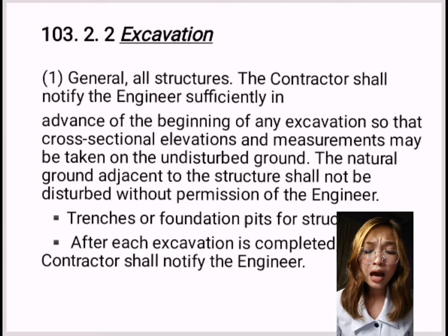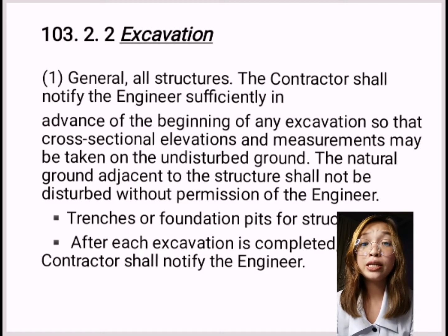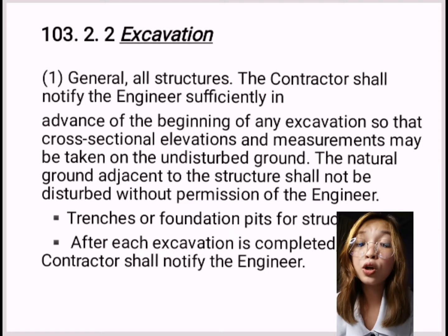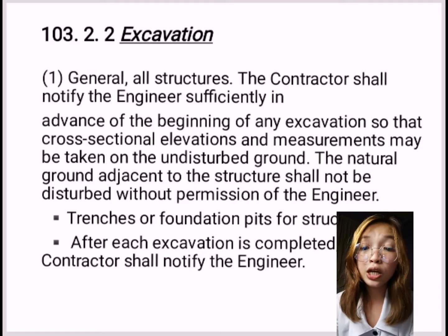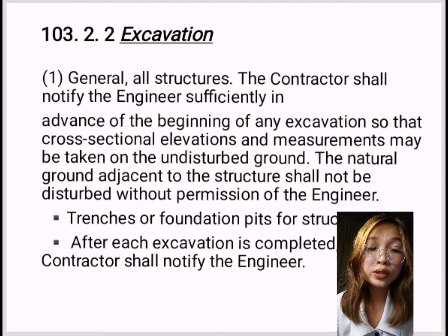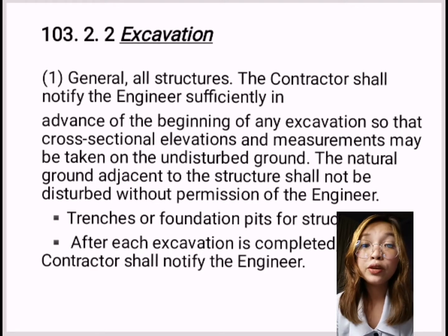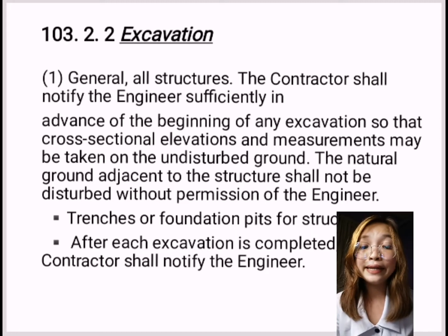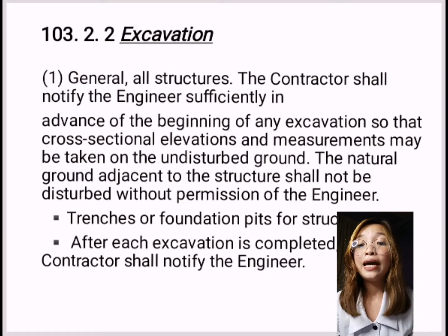So, after each excavation is completed, the contractor shall notify the engineer to that effect, and no footing, bedding material, or pipe culvert shall be placed until the engineer has approved the depth of excavation and the character of the foundation material.